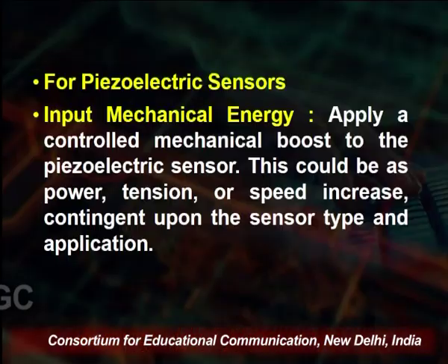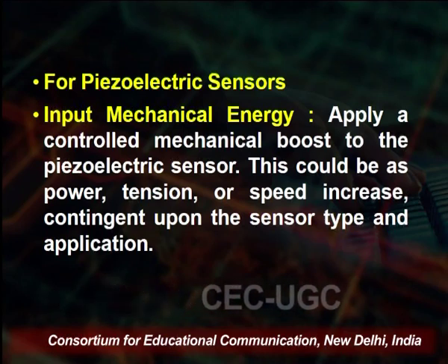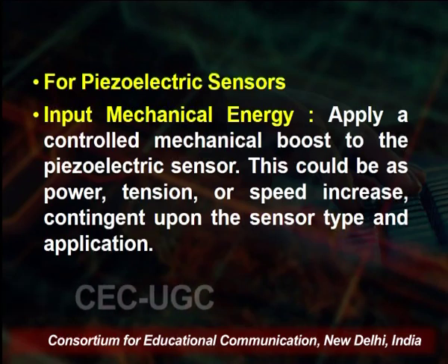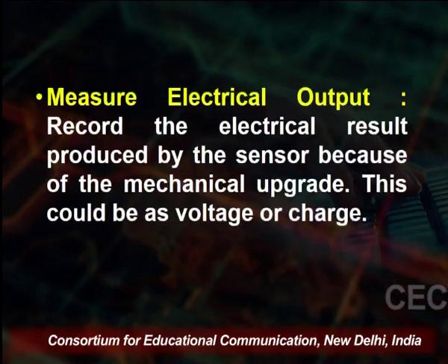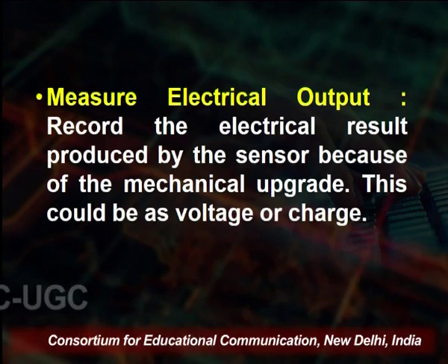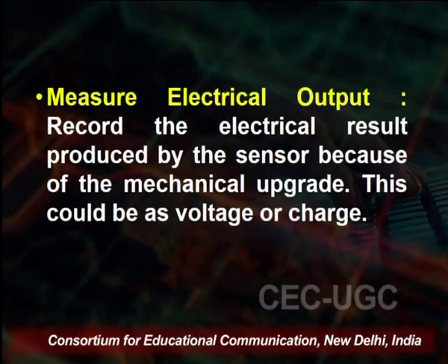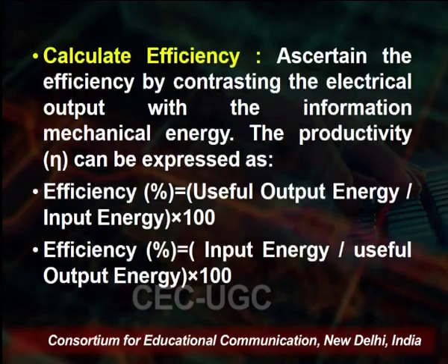Another point for the sensors is input mechanical energy: applying a controlled mechanical stimulus to the piezoelectric sensor. This could be force, tension or speed, depending on the sensor type and the application. Next, measure the electrical output. Record the electrical result produced by the sensor because of the mechanical stimulus, and this could be in the form of voltage or in the form of charge. So it is very important. Now calculate the efficiency.